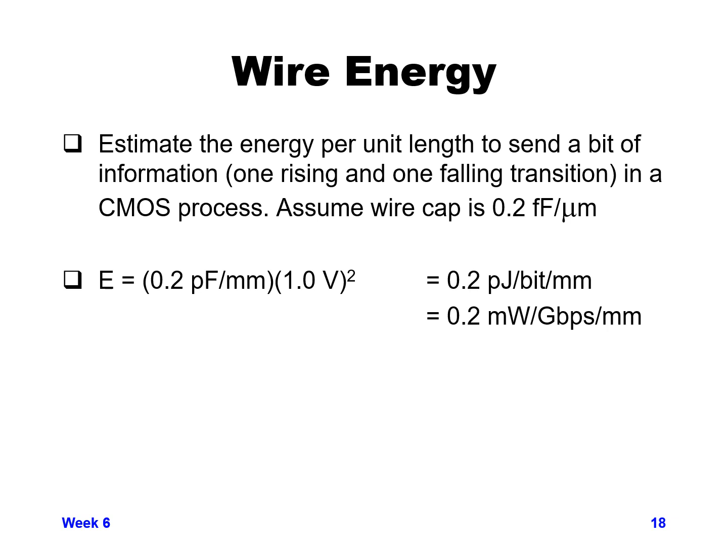If we assume, in a lot of modern process technology right now, 1 volt is a good voltage that is often used still in current process technology. So if we take the capacitance times CV squared, will give us the energy consumed. So that will equal 0.2 picojoules per bit per millimeter.